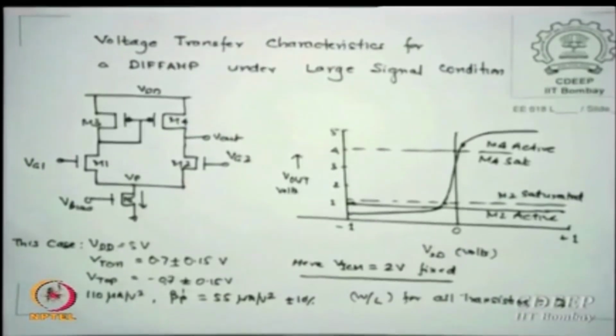So I will figure out where they turn over from non-saturation and then say okay, this is the limit for me. Now in some cases that limit may still have distortion because the linearity may not be as good, but it does not matter, you may actually tune some of the distortions or you may tolerate some of those distortions. Which distortion is most important? Third harmonic distortion. Think of it, why THD is the most dominant distortion problem rather than the second harmonic which most people first derive, but it is the third harmonic which essentially is the trouble creator. So linearity is to be such that the third harmonic distortion is small. So we will see that when the game comes.